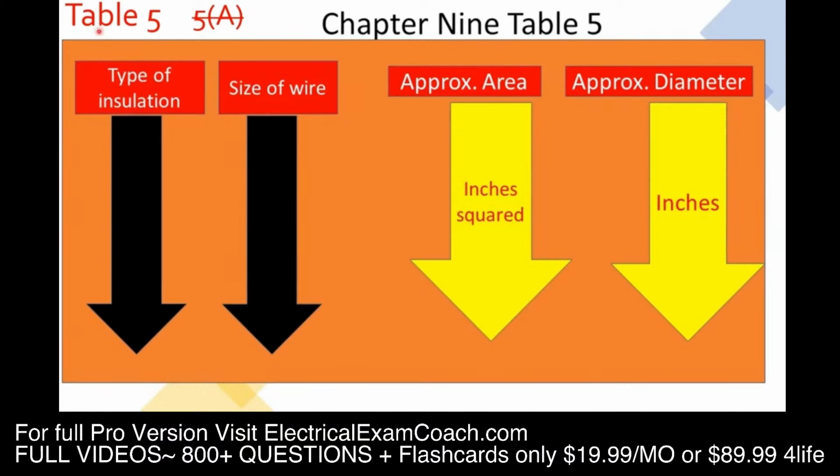So we start on the left-hand side, find our type of insulation, find our wire size, and then find our approximate area in inches squared. Now, let's do some practice questions.